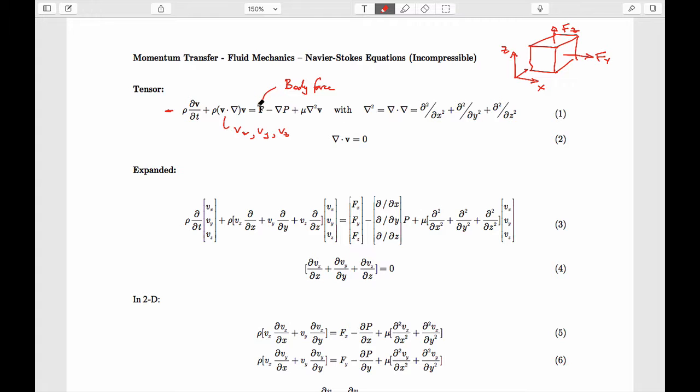And so, in the same way, this would have components fx, fy, and fz. And you could imagine that fz, for instance, you might want to include as being equal to the volume of the element multiplied by density, which is just the body force due to self-weight, which would in this case be the size of the element, dx dy dz, times density. So that's the use of this term.